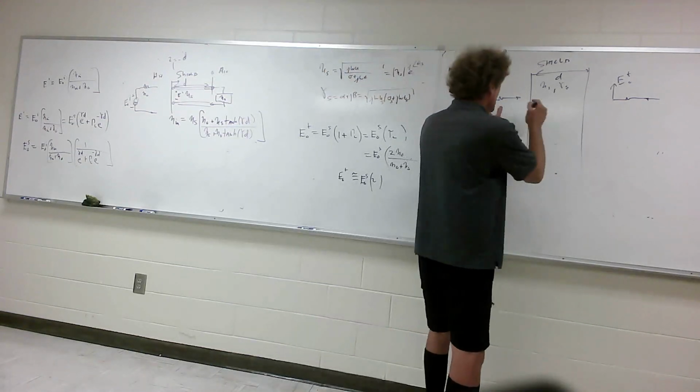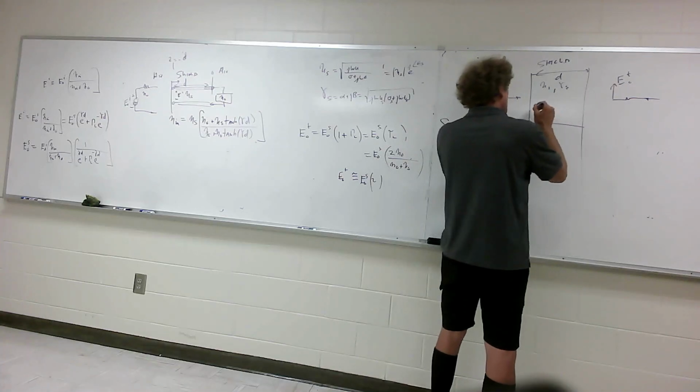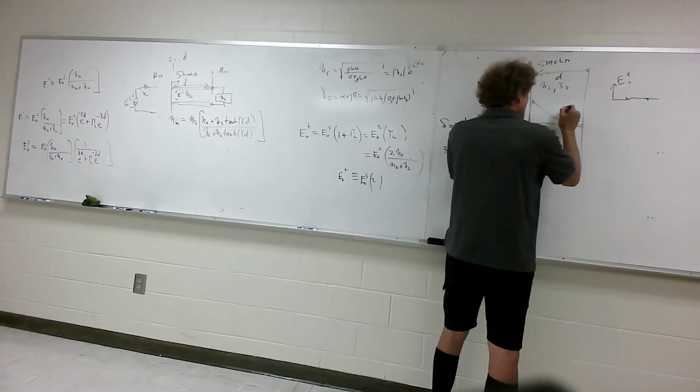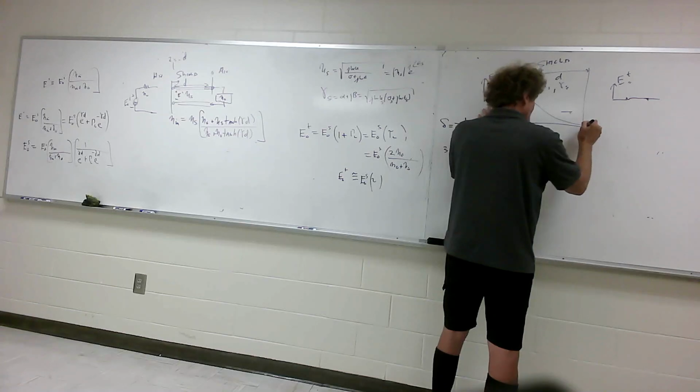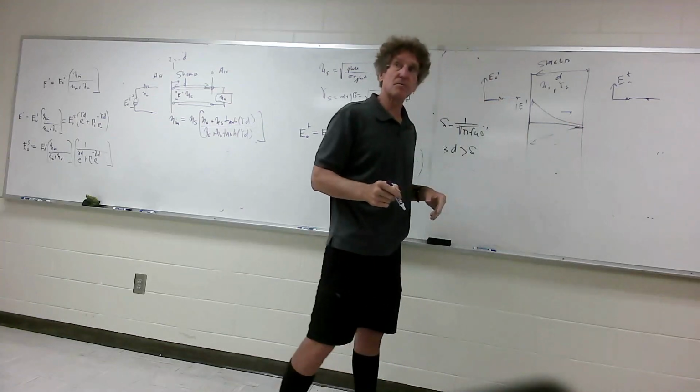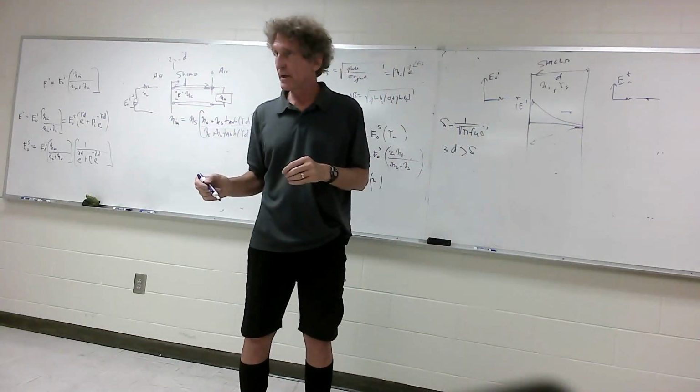Here's what happens: if you were to take a look at the magnitude of the electric field that gets into a shield, if this much gets in, it's going to die out. And remember, this wave's propagating in this direction, so even the reflected wave that's coming back is almost nothing in this direction. So you don't have to worry about multiple reflections. Do you all follow me?